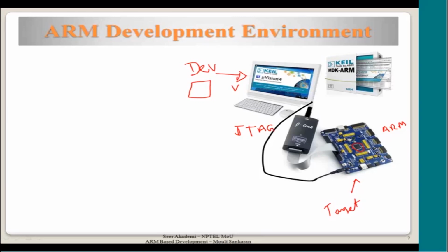And not only loading the software through this cable, we also debug it. What I mean by debugger is the debugger is what is running here. We have a front end tool which will have all the necessary features to look at the program control. You can stop the particular program execution and then look at all the register content.